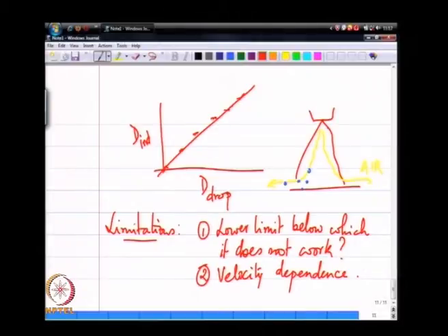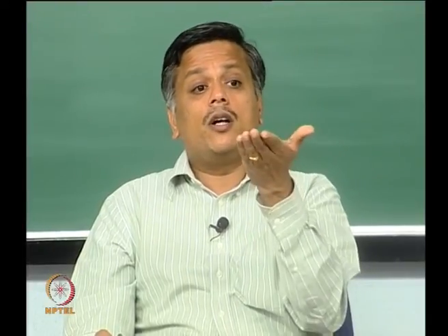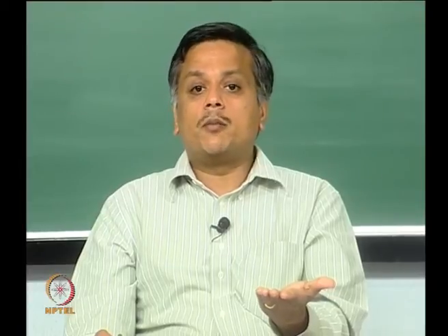So, in other words, I can take the same dripping faucet in my calibration experiment and I can get indentations at different heights below the faucet and get different indentation sizes depending on how far below the faucet my wax plate is placed, just because the same size drop is now impacting the plate with a higher velocity.